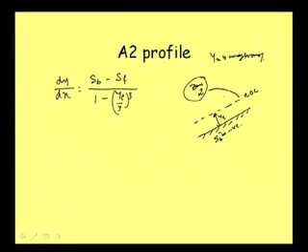Now again for this part, y is less than or equal to yn, and when y is less than or equal to yn, we know that SF is greater than or equal to SB, and here SB itself is negative. So, so far as the sign of dy/dx is concerned, let us go to that.